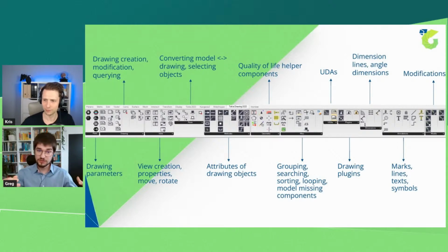So with the drawing link, you can of course create new drawings. You can modify them or get their properties. You can create new views or modify the views, because sometimes it is more rewarding to just create the drawing, the views with Tekla and only edit them after. Then there is the whole thing of migrating, of transferring between the model objects and the drawing objects. Because of course, Tekla drawings are not AutoCAD things, they are not just a set of lines without logic. Tekla drawings are coming directly from the model.